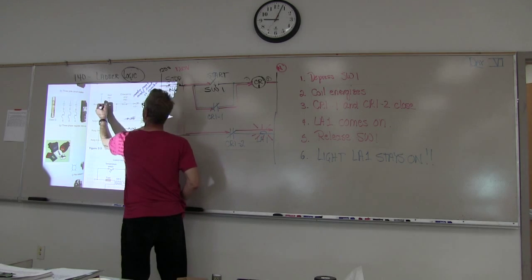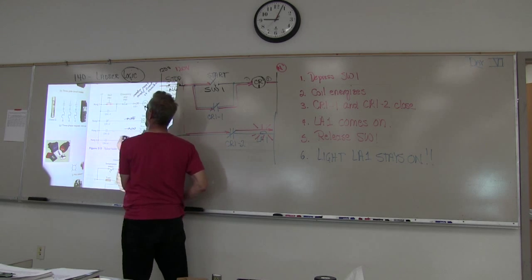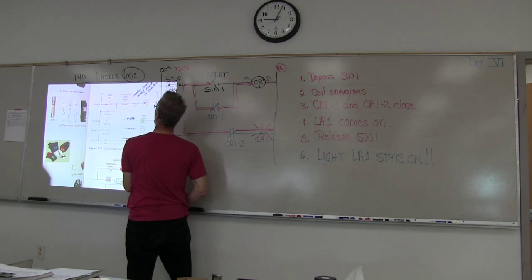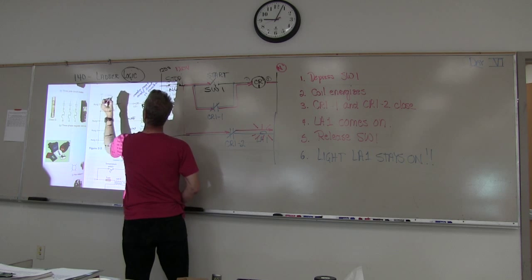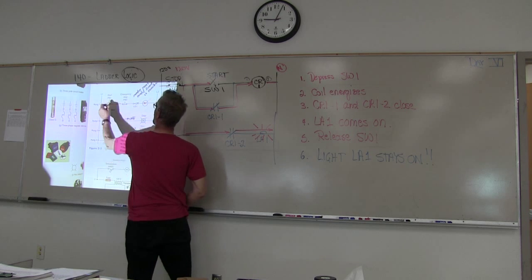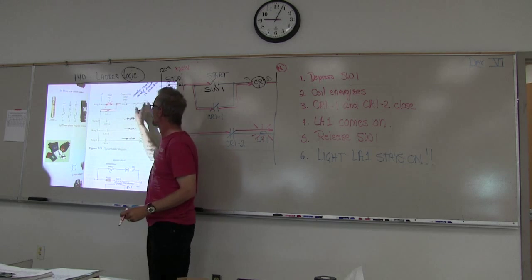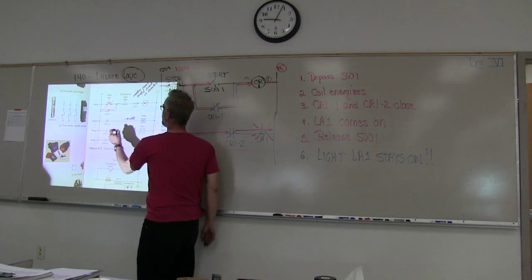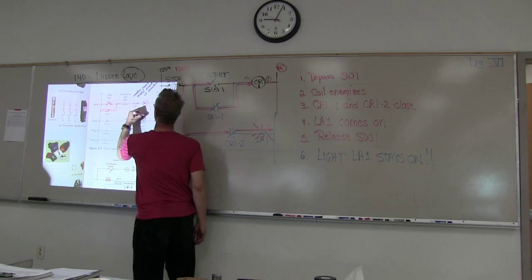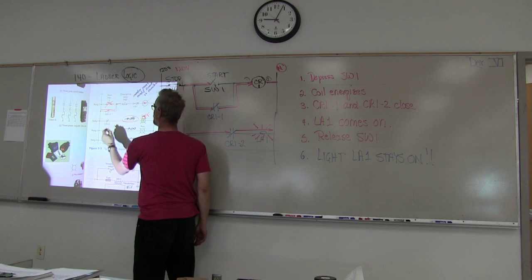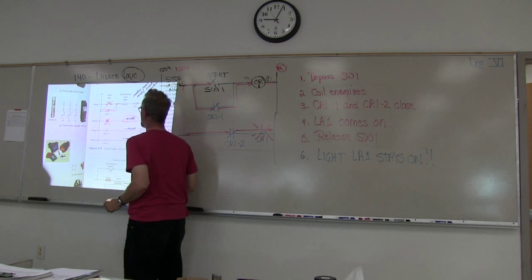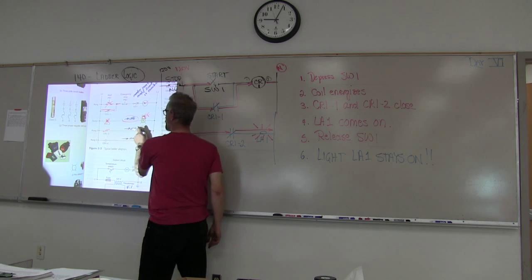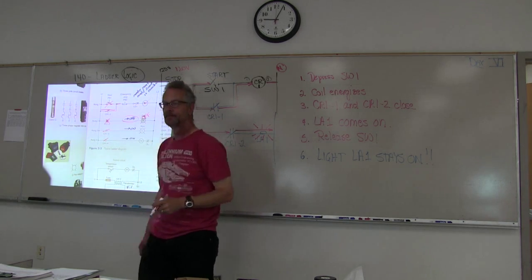As soon as we press this, this closes, right? CR1 turns on, we have this closes, closes, and we can release that at that point. Now we're latched, right? This opens, which turns this off. This opens, this one closes, turning the light on, and closes, turning the motor on.